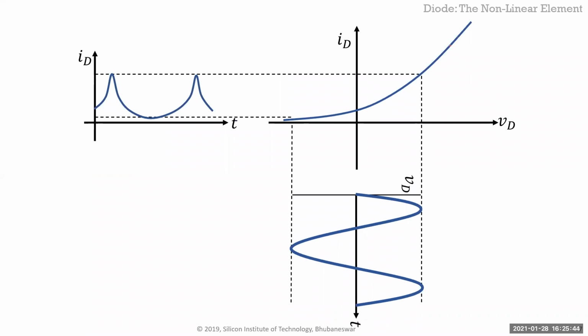So this is the ID-VD curve of the diode. Okay, so you're applying a voltage and this is your current through the diode. So if you apply the signal directly to it, I'm showing a sine wave which is applied. The sine wave is varying around 0 volts with a plus minus volt to it, right? So you're applying that. And I'm showing this dot as the input is varying. I'm just basically tracing this, right? I'm tracing from this point to here and telling you that this is the current for this voltage